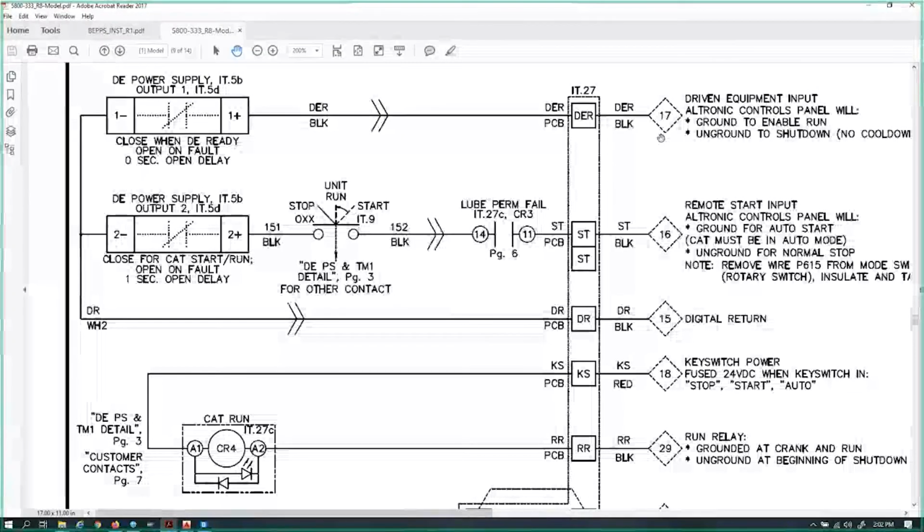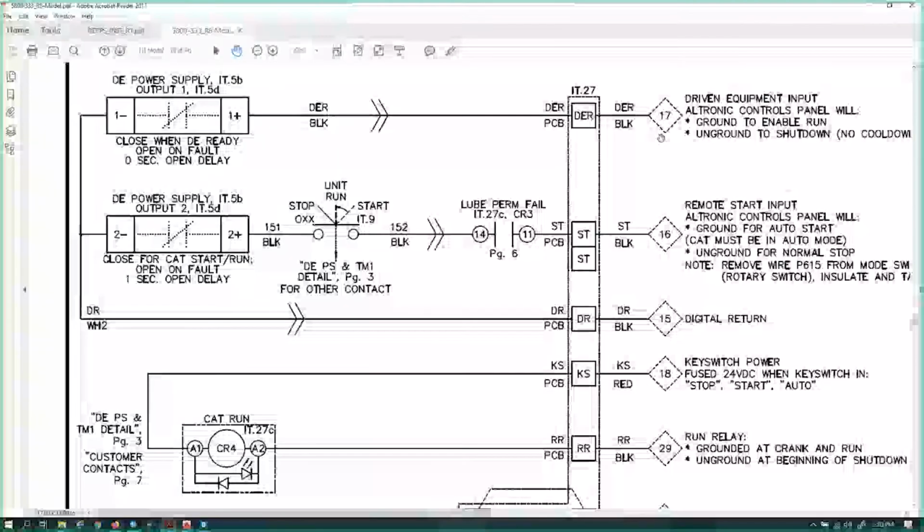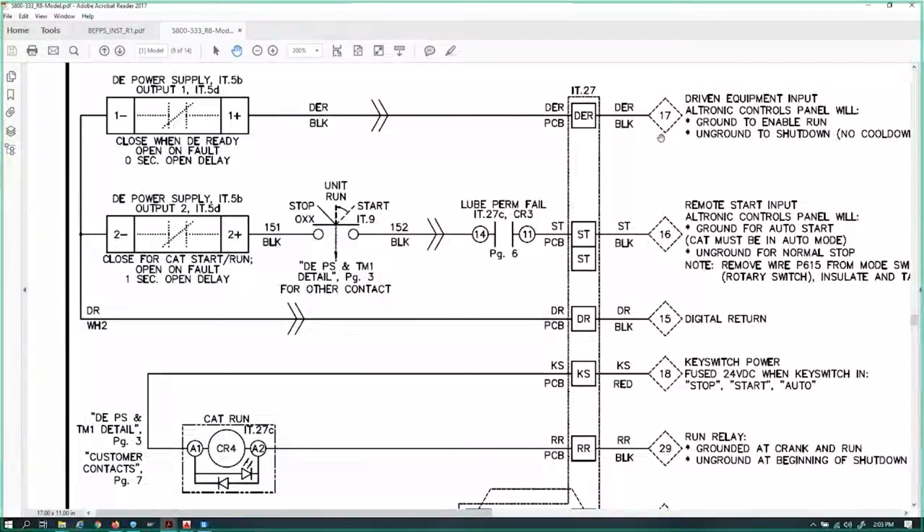Now we could wire them in a closed loop situation or a closed loop switch-in device. So we'd send the 5 volts out through the end device, maybe a vibration switch, and return back. Or we could jumper the two channels together and send one wire out to an open switch. But when the switch closed to ground, it would sink that 5 volts to 0 because it was a non-incentive voltage. Now, for those of you that have been through some of this electrical class, I think we showed it last week too, that's also a reference of what we call voltage potential, which is why I like to use that video so much.